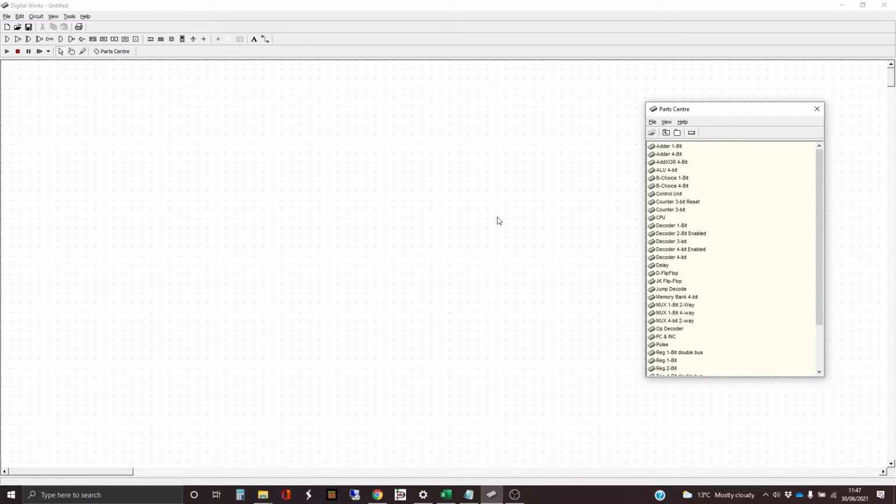We're going to load in the data and the op from the two memory banks. So if you remember, if you've been following through, we've got two memory banks. We're using a modified Harvard kind of architecture in that we've got one address register that accesses two separate memory banks.